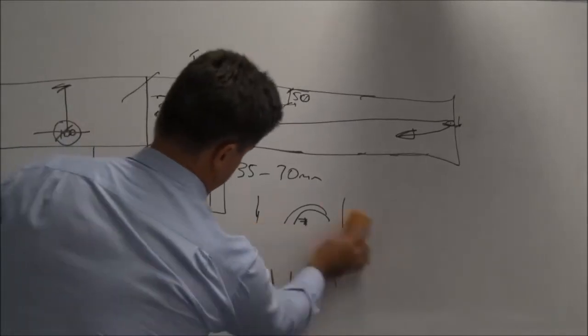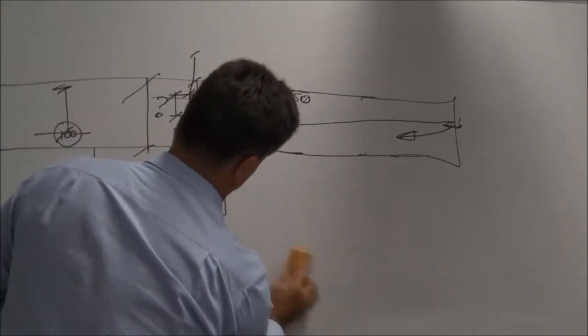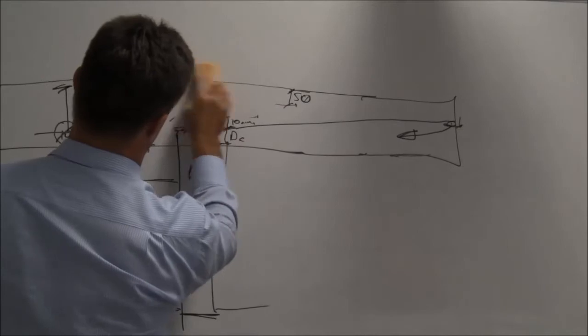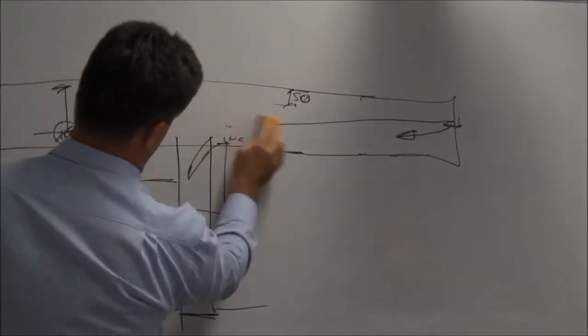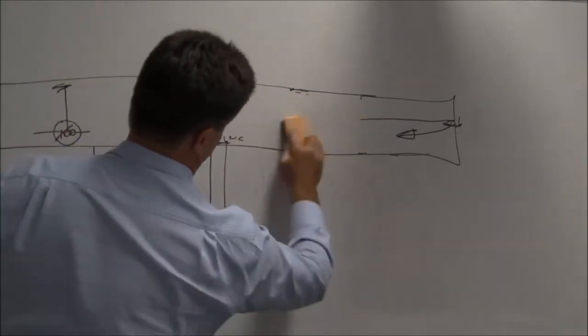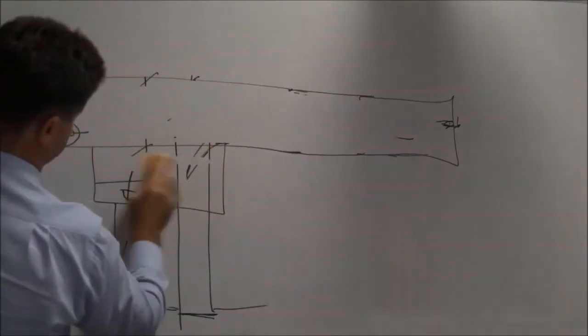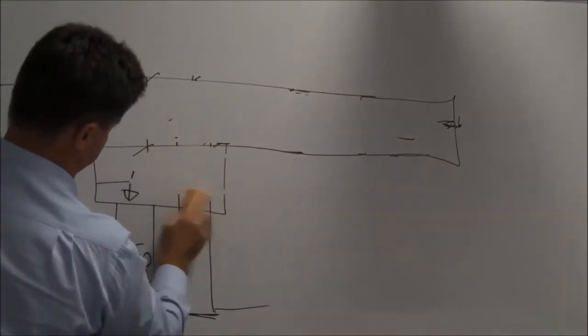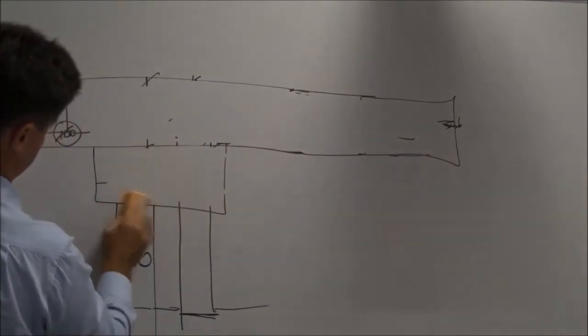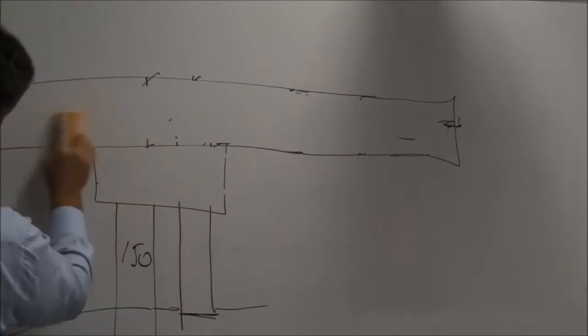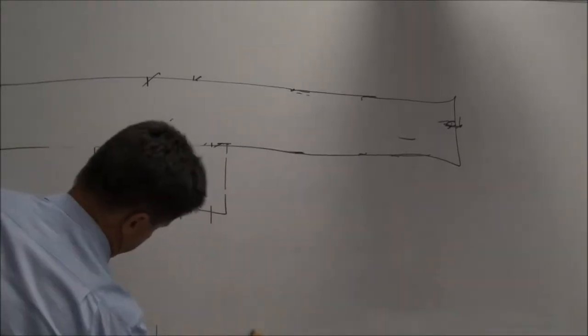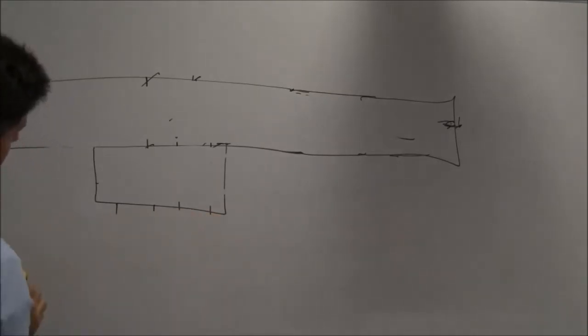The other thing you need to be careful of too, and it's going to be covered under volume 2 when you understand the sizing of a stormwater pipe, is you need to be careful when you're doing box gutters, which we've had to go back and fix up on a particular job that I'm aware of, where the guy's installed his box gutter and sump.